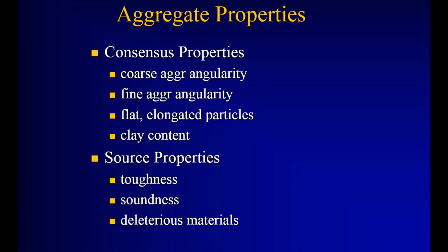But basically, if it was shot rock from a quarry that was run through a crusher, all the -4 was considered manufactured fines. If you were running a pit face and running that material through a crushing and screening operation, the only way that fine aggregate or -4 could be considered manufactured fines is if the material, the pit run material fed into the operation, was scalped on a 3/4 inch slotted screen.